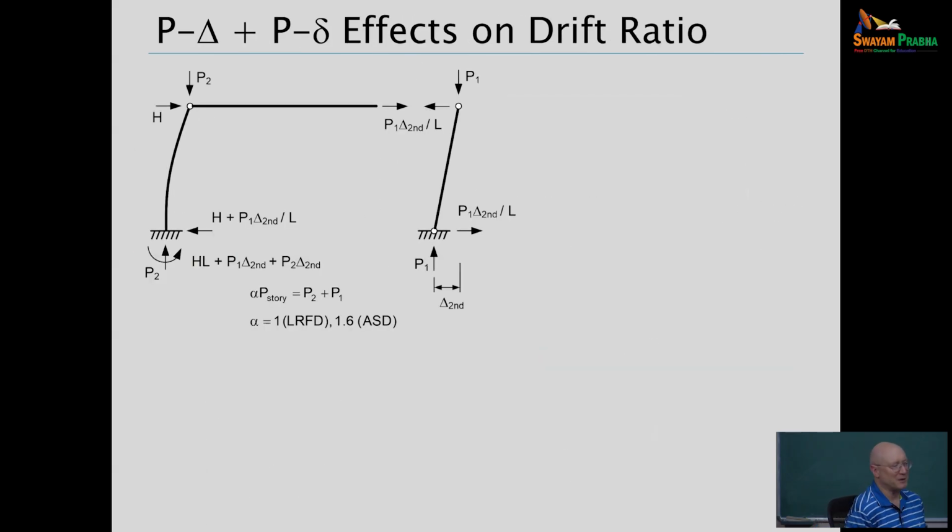Now let's suppose we've got some gravity load also on the lateral load resisting system. So the leaning column on the right here, that's just a surrogate for a whole bunch of gravity framing that's just columns that aren't providing any stability or any resistance to load themselves, but are carrying vertical load to the foundation. So I've got my one column here on the right that's representing that, and then the cantilever is representing whatever is providing my story sidesway stiffness.